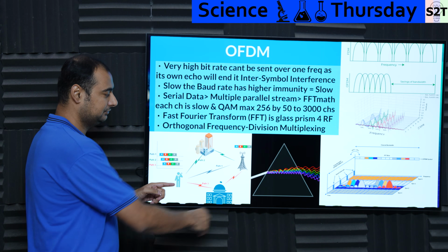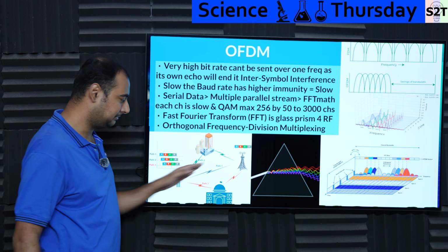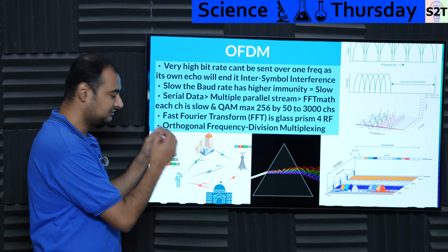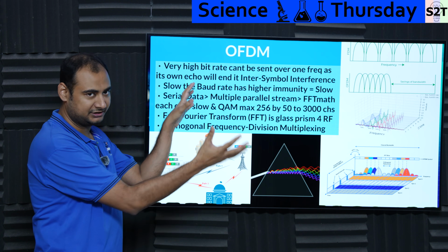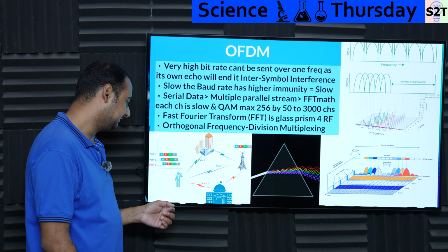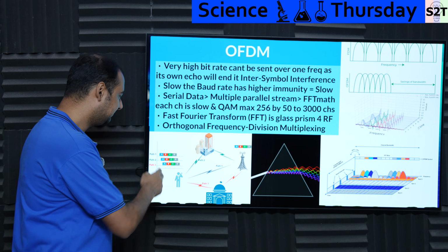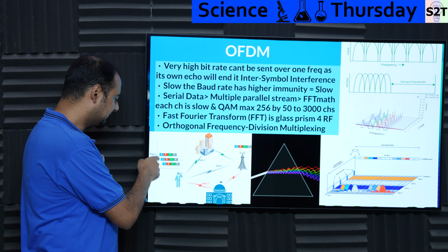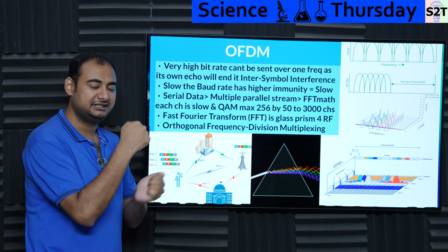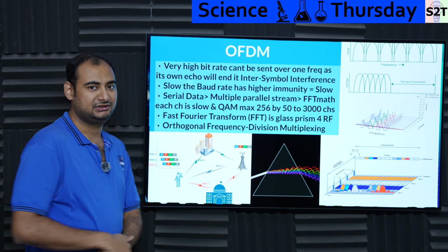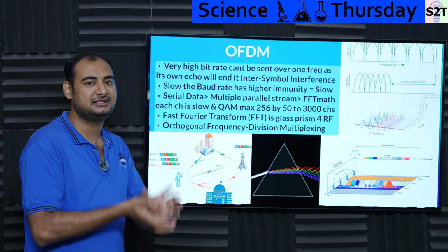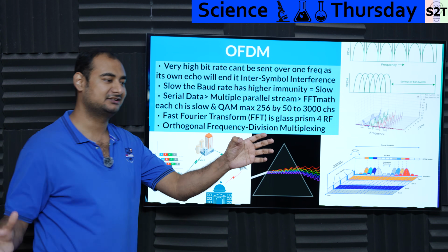Physics is like your mobile phone, your tower, you send a signal, tada! So path A is the signal. But here's the deal. You are not living in a world where radio is traveling via optical fiber. It is omnidirectional. You're going boing, this is going boing. So it is bouncing from everywhere, meaning buildings, other buildings, stuff like that. So if you are switching way too fast, when your antenna is receiving it, path 1, path 2, path 3, they are so minutely apart from each other, they are interfering constructively or destructively. Basically, they are destroying the symbol, which we call inter-symbol interference. The data packet itself is getting destroyed because one data packet arrived, another data packet, bam.